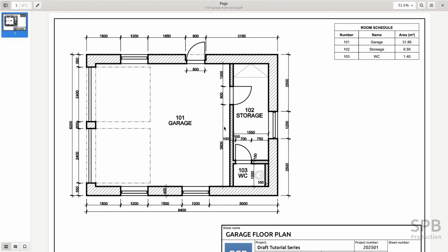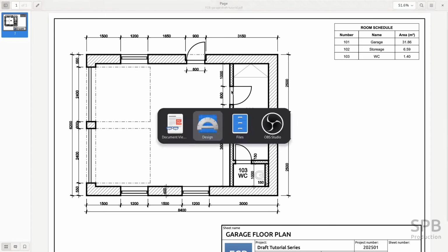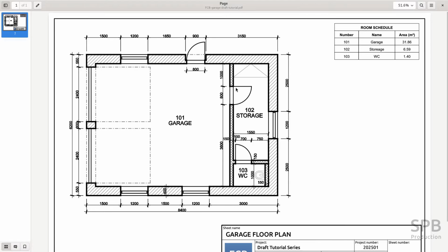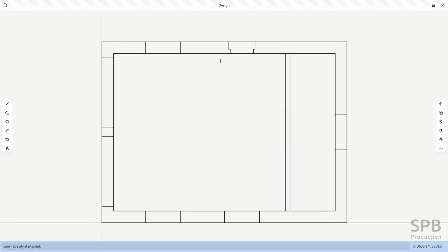So now we've got these walls created, and I want to cut off these spaces for the windows and doors. So I still have got to create these lines. So again, I will create this one here, select it and move it 1000 millimeters to the bottom, and then the width of the door is 800 millimeters again. Now I want to cut away these parts of these lines.